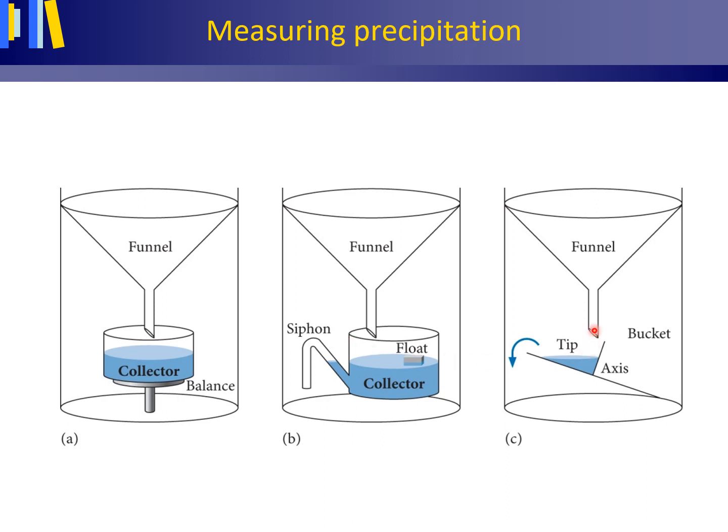In a tipping bucket rain gauge, the bucket tips over each time a certain volume of rain has fallen, usually corresponding to a 0.2 millimeter rainfall depth. By registering the timing of the tips, the average rainfall intensity each time the bucket tips, as well as rainfall depths over longer periods of time, can be determined.